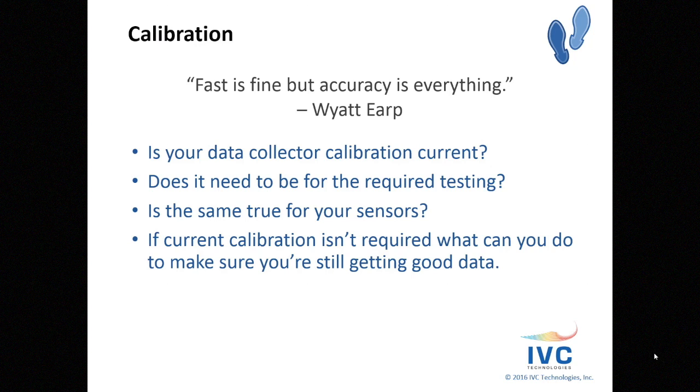Some of the testing that we mentioned earlier, baseline tests, commissioning tests, testing to an OEM standard, all of these may require that all of your data acquisition, including your sensors, have to be in cal. In fact, very often you may have to provide the calibration sheets along with your test data at the closure of the project.